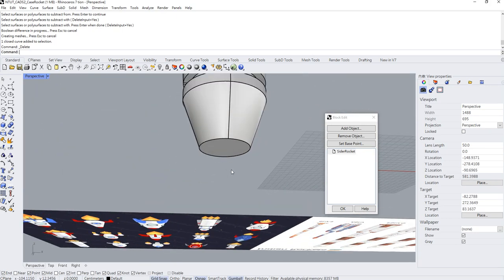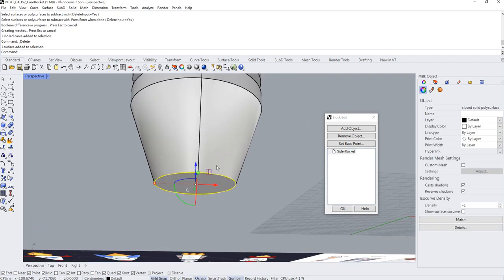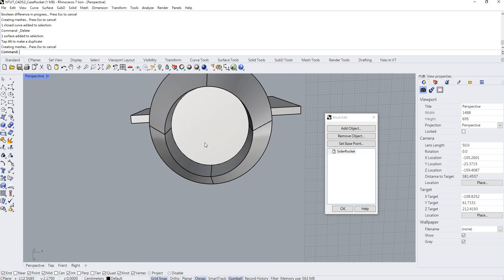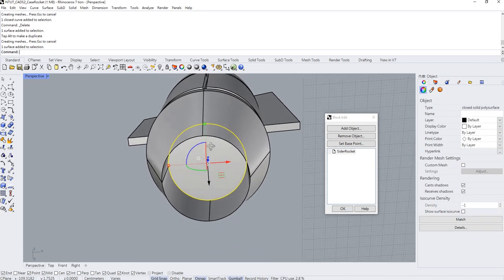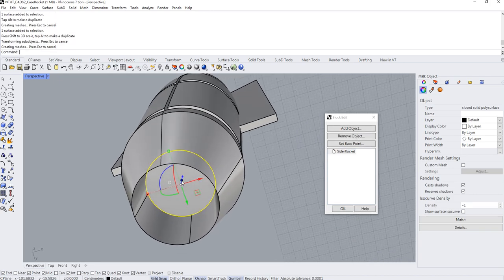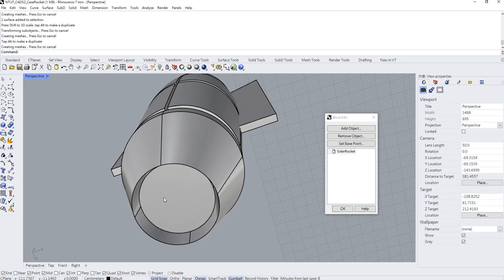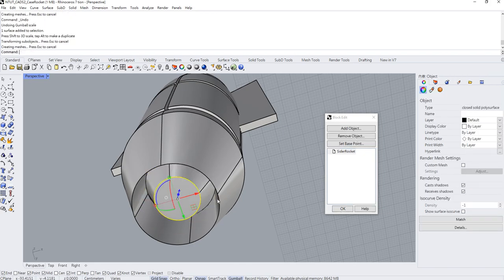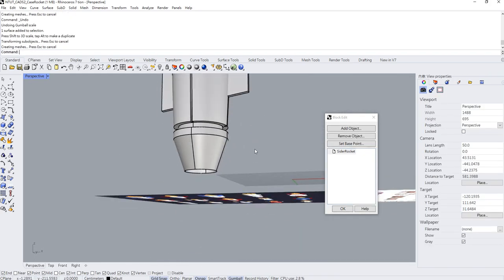Very simple. First thing is I want to choose the bottom face, hold on your shift and the Ctrl key, and you can choose the bottom face, and then let's type in extrude. Right? So now I'm going to extrude the inner area of this injector. Shift and Control key again, and hold on your shift key, make this one smaller, and then extrude again. Hold on shift and Control key, make this one, and then shift key, make this inner part smaller. So now we will have the inner part.